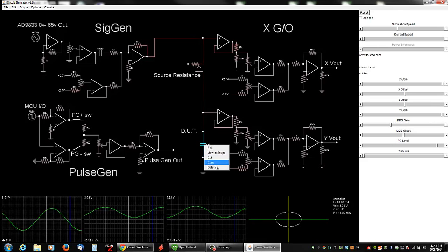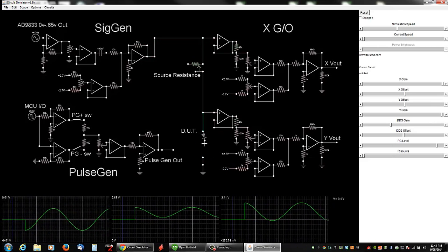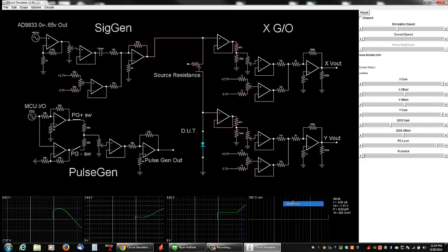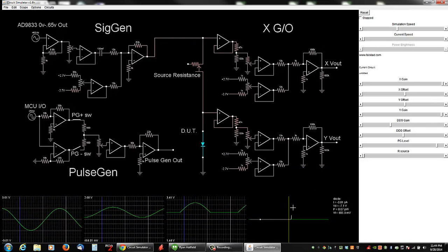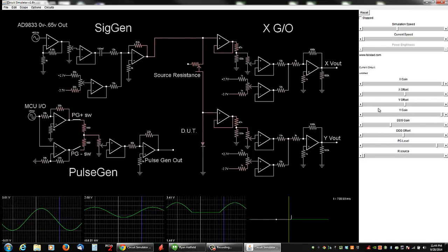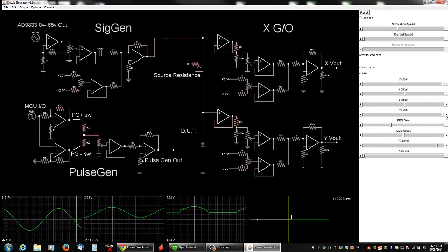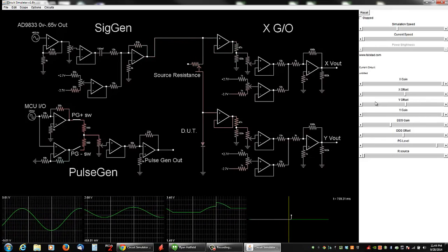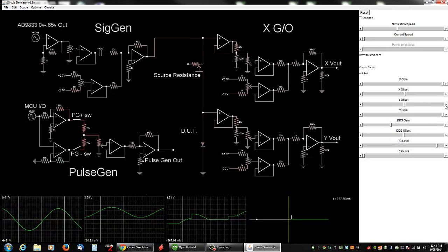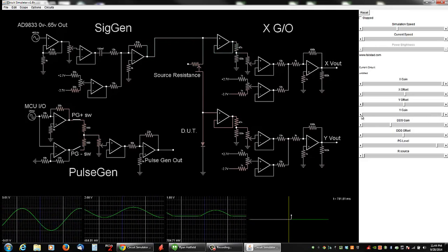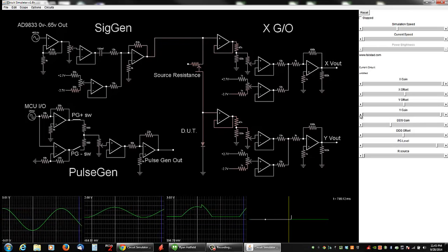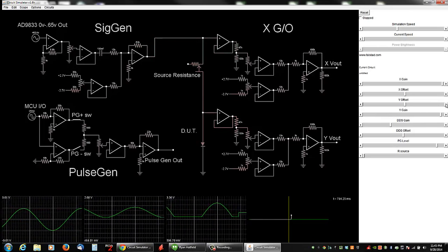Now we'll go ahead and get rid of this capacitor, and we're going to put a diode in there. Go show it in the scope. V over I, no current. There you go. Now I've got to rescale my gains again. Oop, too far. Turn up the gain just a little bit. Turn it down.